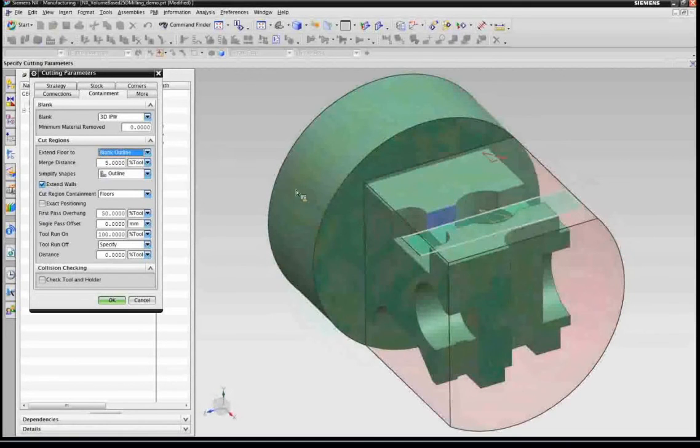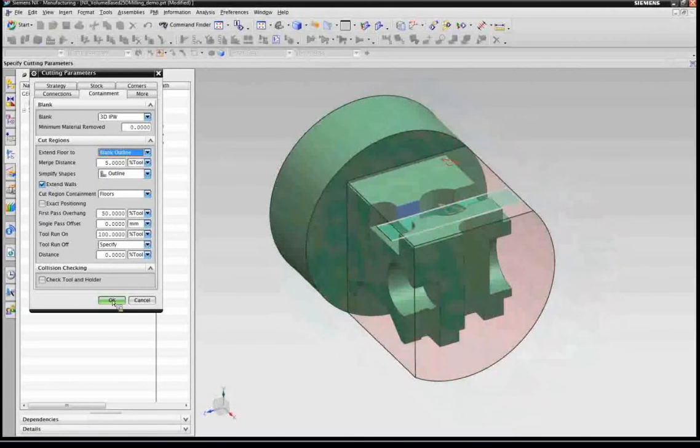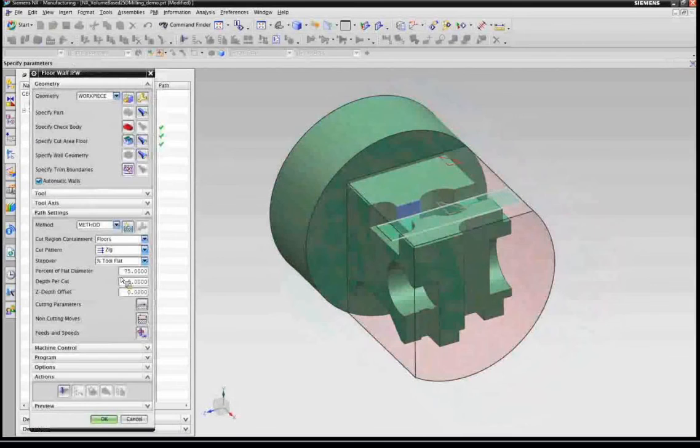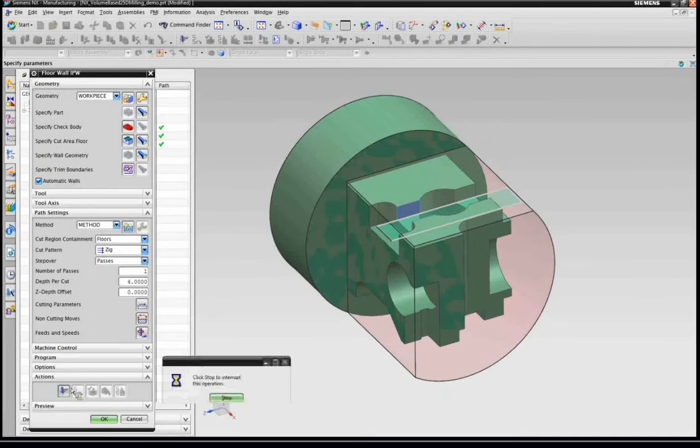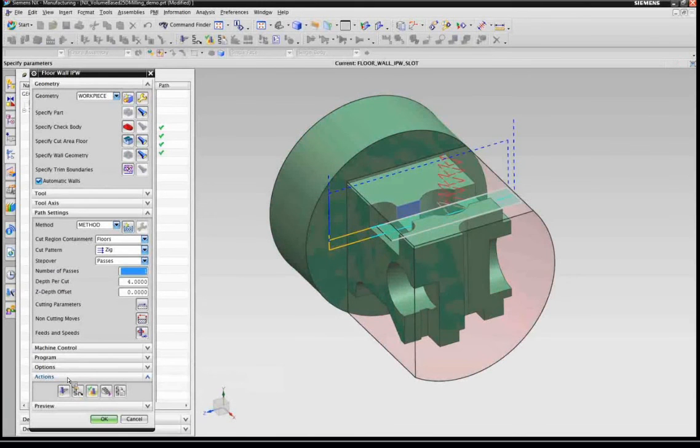So I didn't change anything. I just tried to show you how all of this works. It came up with this automatically. Typically, all I would do is say I want a depth of cut of 4 millimeters. I want a single pass through this slot, which is hard to accomplish. Usually, you either get none or you get 2, and this way, it will give me the result I was expecting. 2 depths of cut, single pass, straight through the middle.